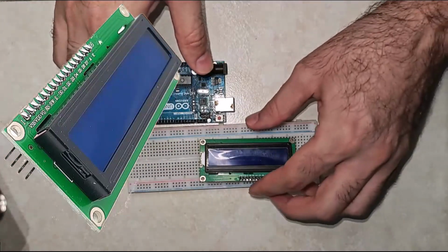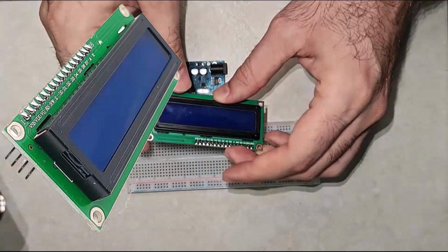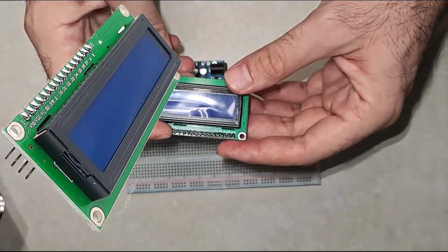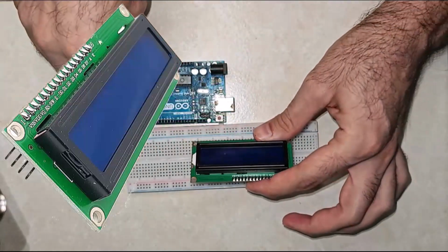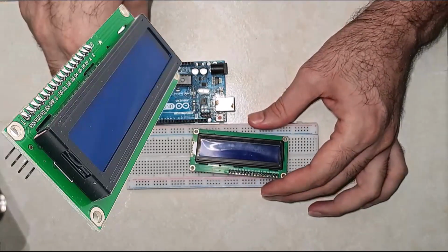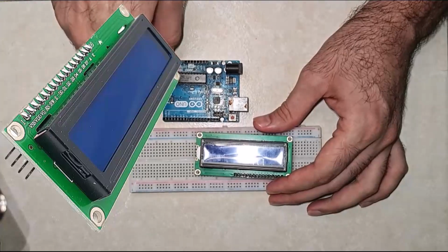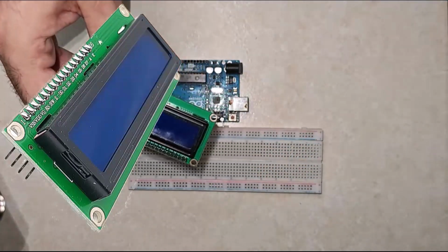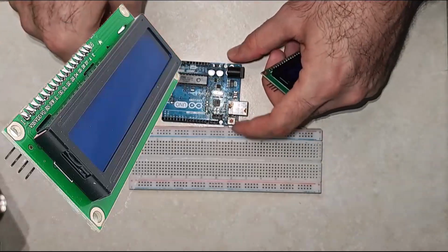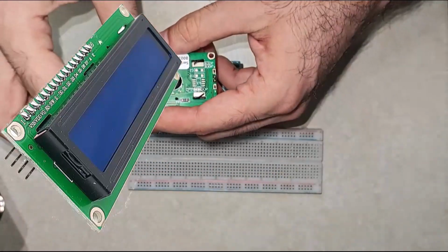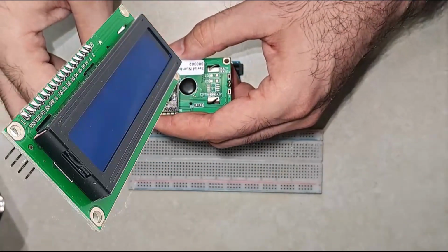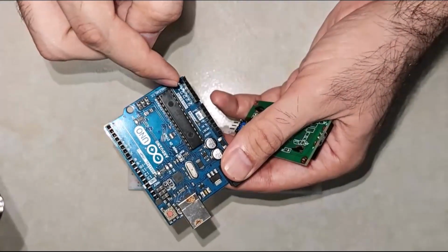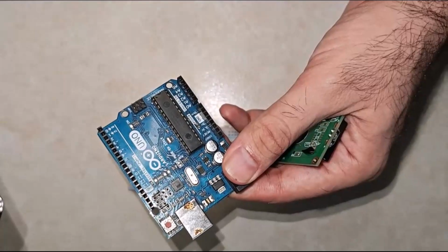I hope you understand what I mean. It's very easy. For now, don't get confused, guys. I won't explain more about why we have to use only A4 and A5, because if I make it more advanced, you may get confused. For now, just remember that because you have the I2C protocol and want to use it, you are only allowed to use pins A4 and A5.